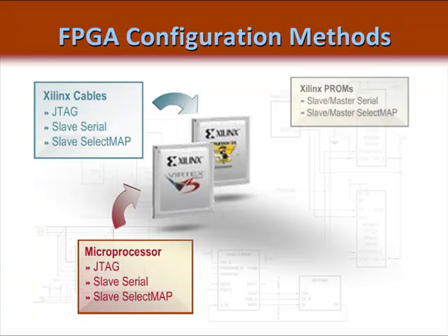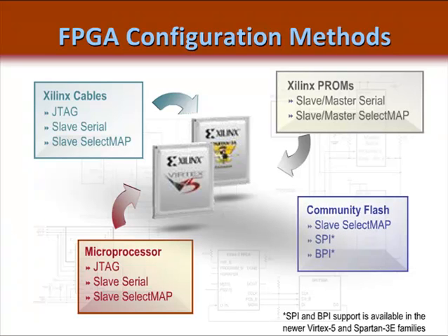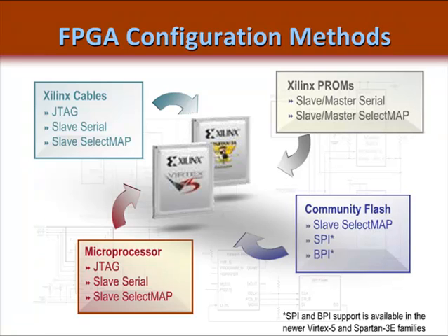Configuration can also be completed using the Xilinx Platform Flash PROM. These configuration schemes usually use the FPGA's built-in configuration logic to control the FPGA's configuration. With these components, the FPGA usually configures itself. These configuration schemes require the user to buy a PROM, which has some additional cost, but these configuration schemes are usually the easiest to debug since the control logic is already fixed as part of the FPGA. We will talk about the Xilinx Platform Flash product in the Basic FPGA Configuration 2 module.